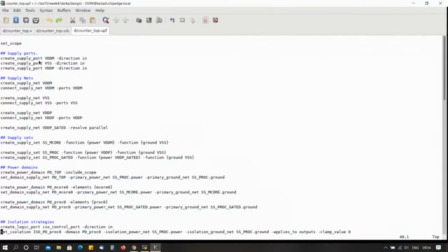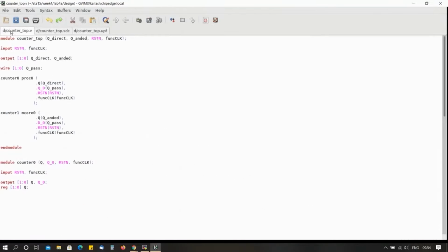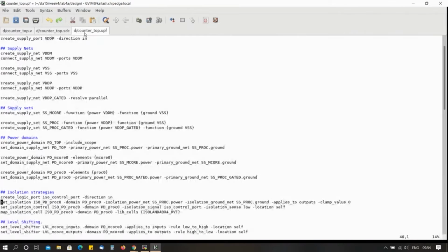So here, this is also considered a UPF. Where will you get this file from? From the low power team. There is a separate power team available in your companies, and those people will provide you this UPF file. For the same design you have, they will write some constraints, consider them in UPF format, and give them as input to your synthesis tool. Based on those inputs, you perform your logic synthesis based on your UPF files.